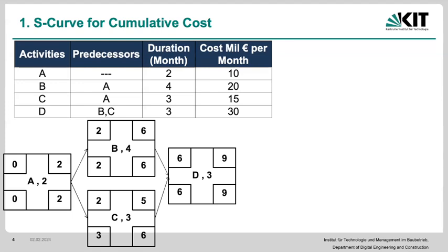And then we talked about the definition, and that definition was total float, right? We said that if we have the top and the bottom of either one, so either early start and late start, or early finish and late finish, and these two are the same, what does that suggest for a particular activity? Exactly. It's a critical activity, or the activity is on a critical path. So if this and this are the same, either the left or the right, what does that mean?